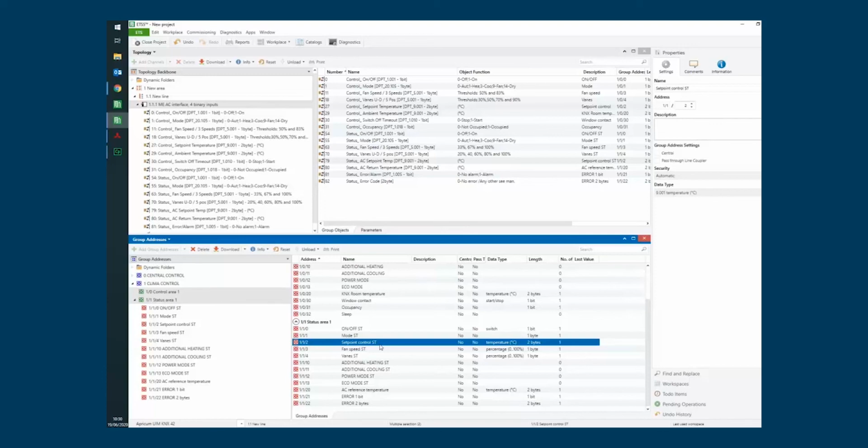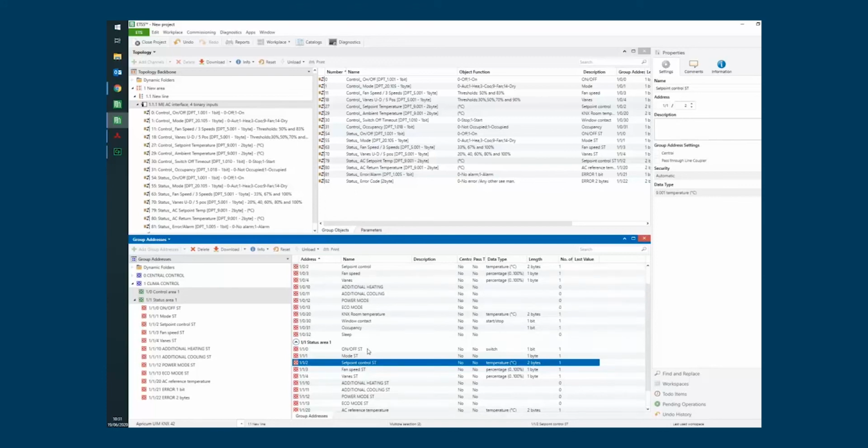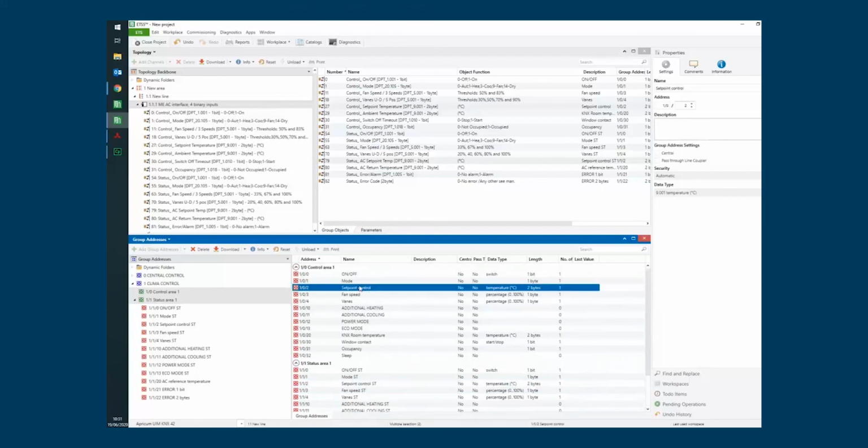So it won't make sense to display for the customer that the AC unit is at 23, because normally the user doesn't care about the real set point in the AC unit. They are more concerned about the feeling inside the room. So this temperature I have linked for our own understanding and to have it available. But in case you want to know at any time the set point, you should use this one.